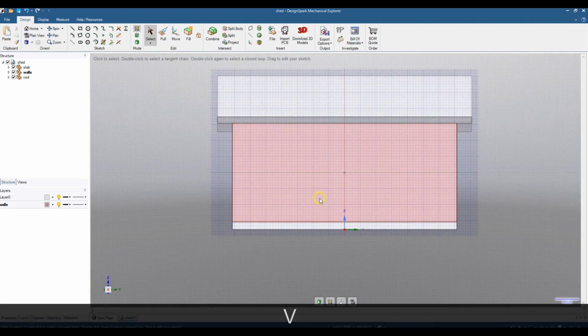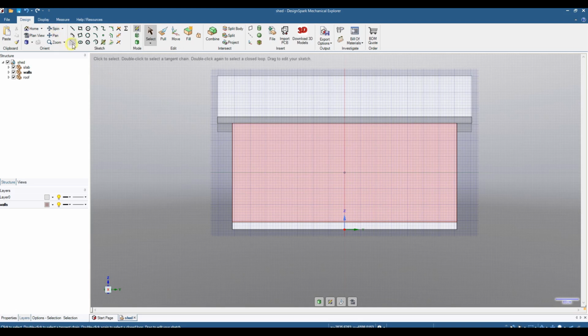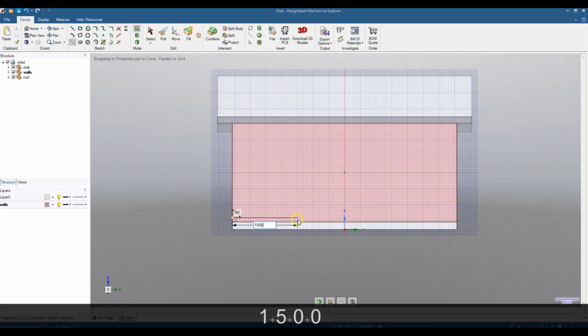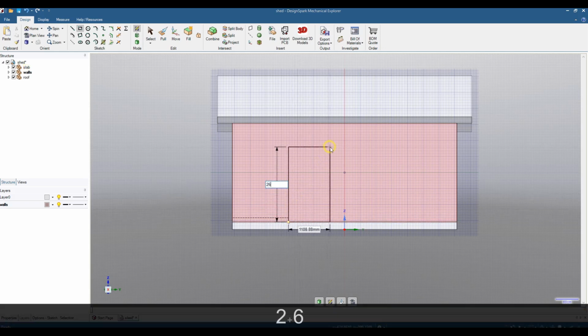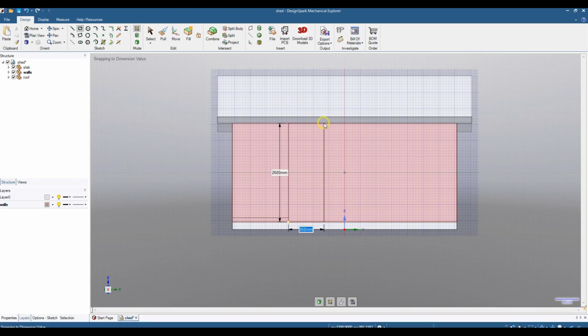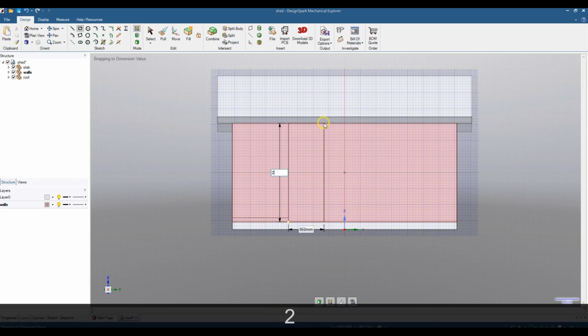If you want an accurate placement, then you can use a construction line. Press R for rectangle and drop down to the slab from the end of the construction line. Drag a rectangle of 2,600 by 950 millimeters. That's a bit over the top. Change that to 2,000 millimeters high. If you have accepted the door, then you can use Ctrl-Z to undo. Click to finalize.